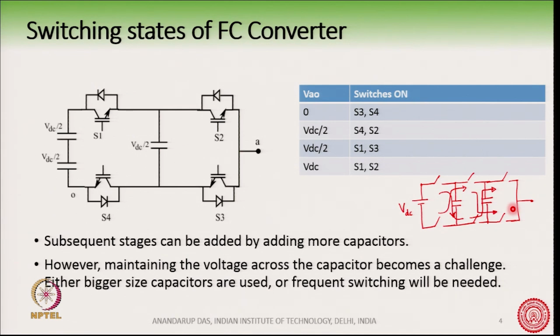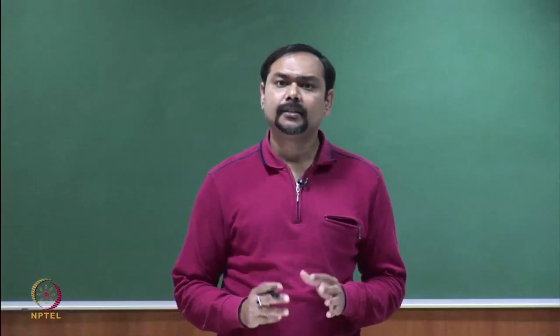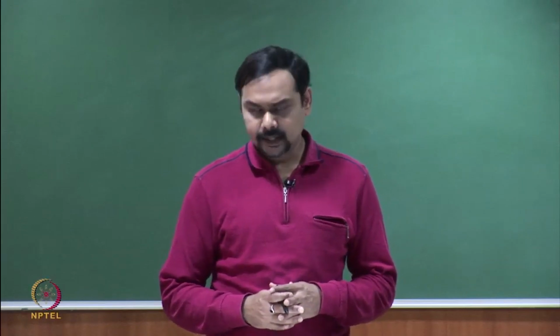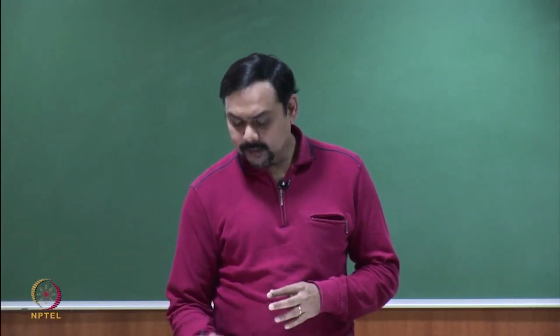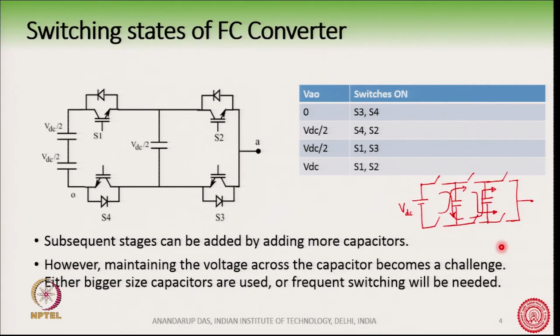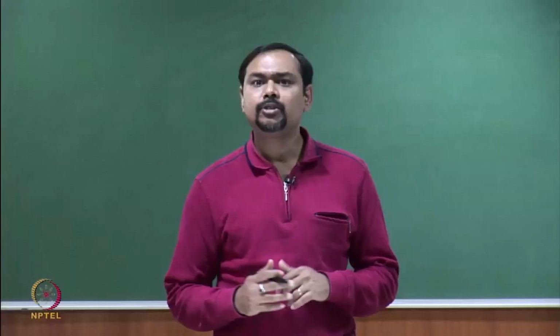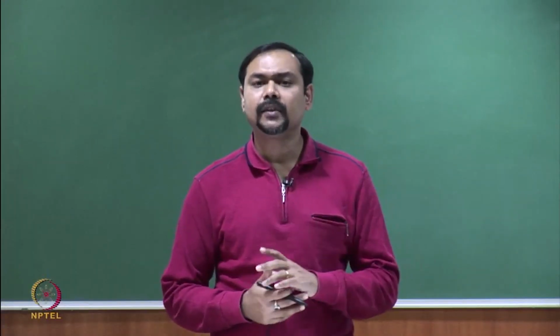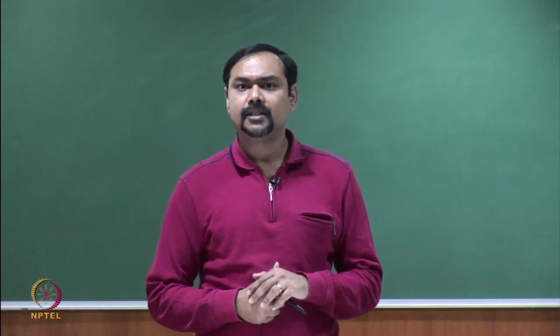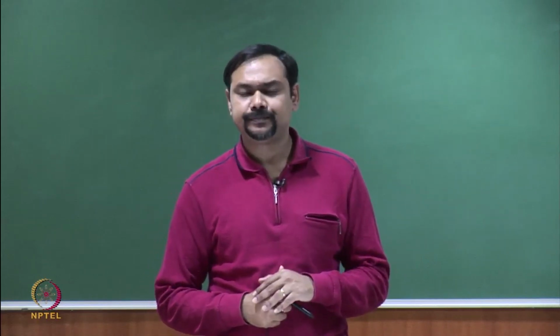In the case of multi-level converters, we know that the load current can be quite high. As a result, these capacitors must be big in size, otherwise because of the high magnitude of the load current, they will quickly charge or discharge, and their voltages will quickly change from the nominal value.